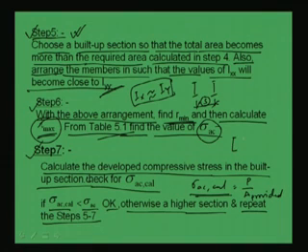Now, this is not the end of the design, because when we are providing, say, 2 channel sections, 2 individual channel sections have to be tied up in such a way that the section is acting as a whole, as a group. So, by the use of lacing or battening members. That will come later, but before that let us go through one example through which we will see how to design with these steps.